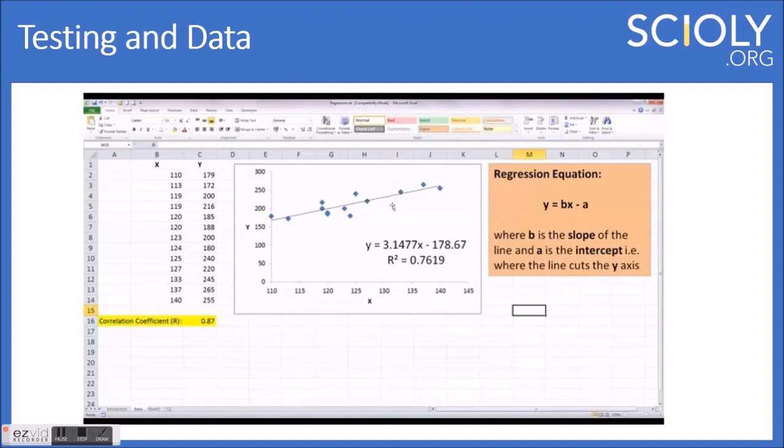What we did for 2017 kind of demonstrates this. We collected data for the wheel, the caliper angle, which is essentially the axle angle. We also collected data for what angle we were aiming the vehicle at initially, because we would offset it.